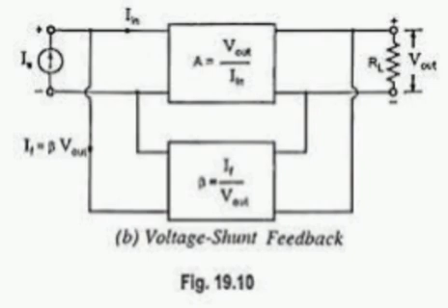AC analysis of a differential amplifier. For the non-inverting input, AC emitter current IE equals V1 by 2re, where re means emitter resistance. AC output voltage Vout equals IC RC, equal to V1 RC by 2re. Voltage gain for the non-inverting input, Vout by V1, equals RC by 2re.